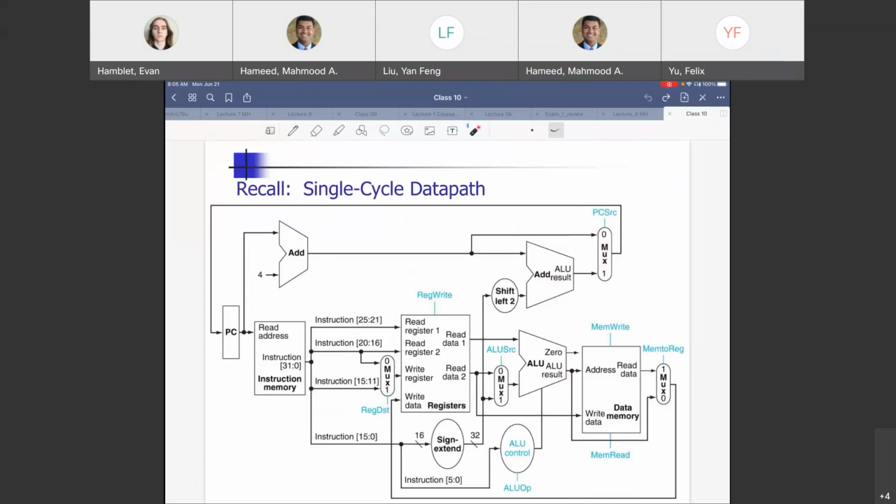You're always looking at, if it satisfies, jump to this branch address. If it doesn't satisfy, think of the branch address as becoming a 0. Then it's going to be the next, PC plus 4, right? So think of it happening in a loop. If it happens, you jump away from PC plus 4, because if you didn't, you would jump to PC plus 4, which is the next one, right? You are essentially jumping away because you are already executing PC.